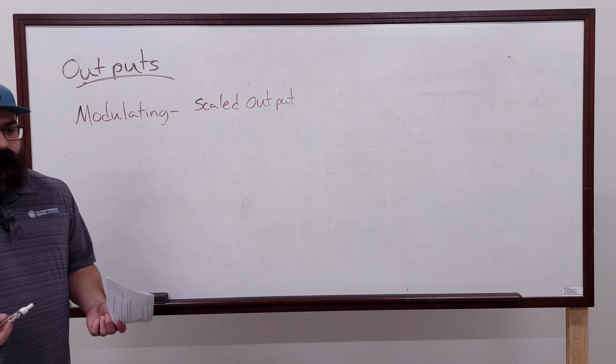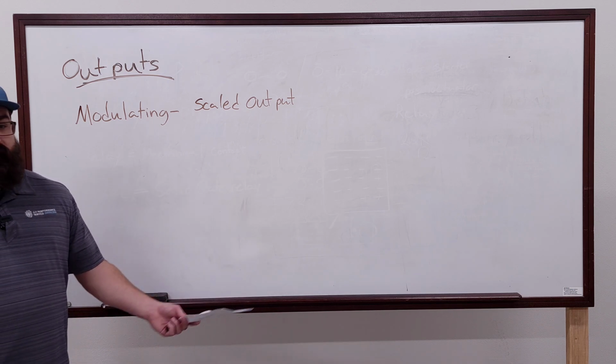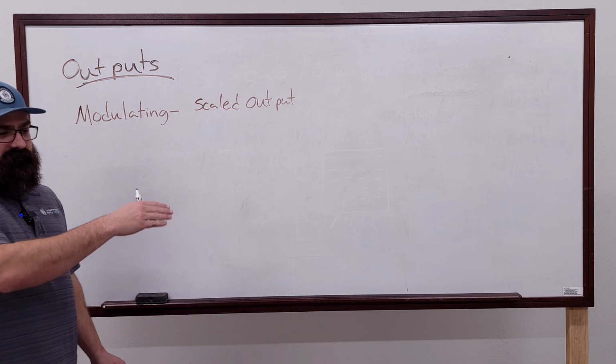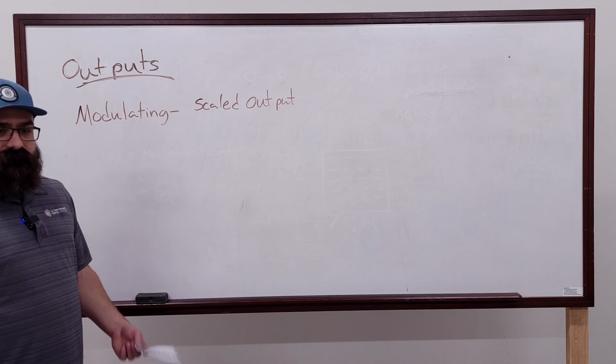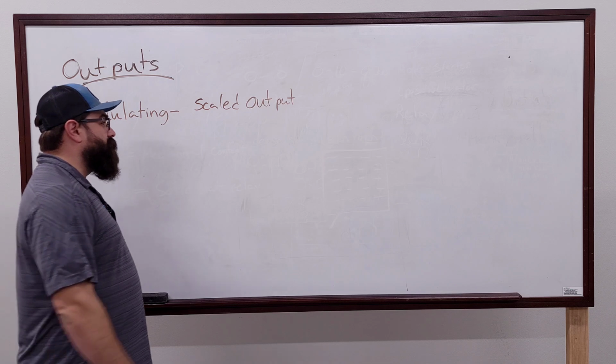for whatever, right? Like if you have a drive, right? Takes a 0 to 10, that drive converts the 0 to 10 to static pressure. It knows, hey, I need to ramp this drive up based on that output.